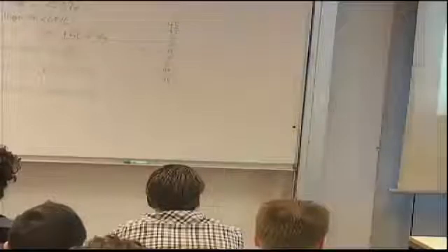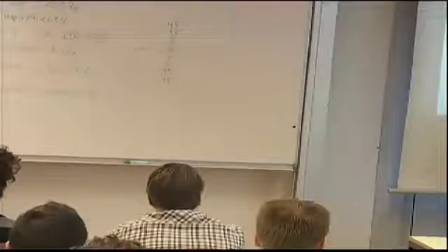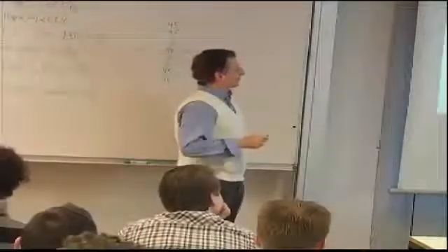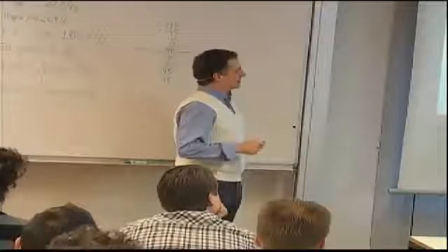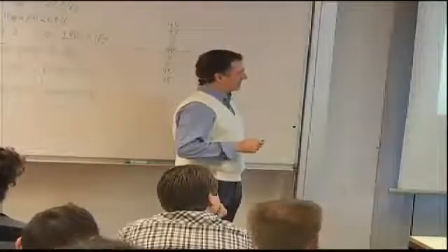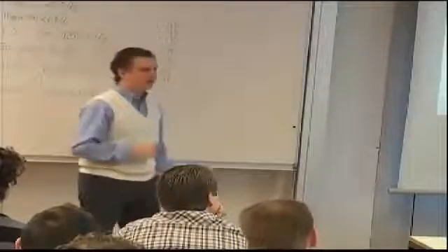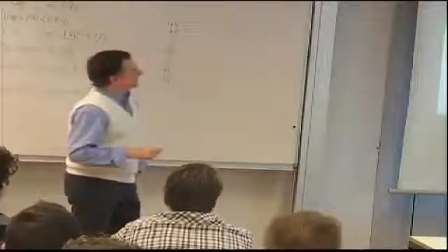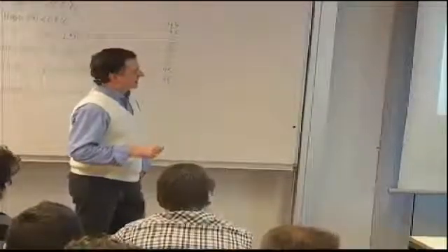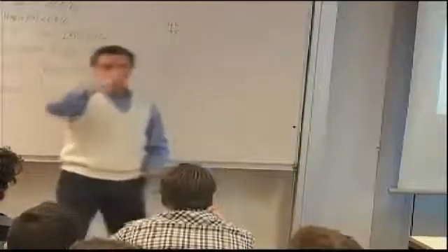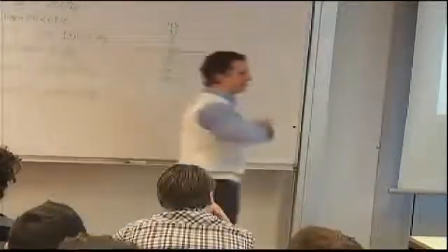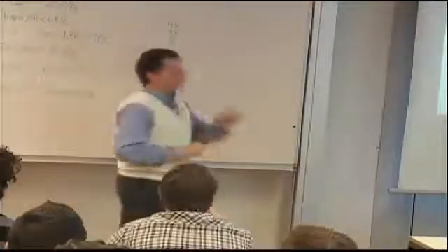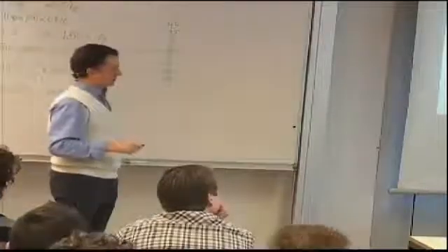In order to do that, we need to determine the stresses for this problem, and we make some assumptions. It's a homogeneous orthotropic plate. The layup is symmetric, so the B matrix is 0. That the layup is balanced, so the A16 and A26 terms are also 0. That's just for algebraic purposes to make it slightly easier. And we are assuming there's no twisting, bending, coupling. We mentioned last time, I believe, that if you have anti-symmetric layups or layups using only 0s and 90s, or I'm telling you now, layups using only fabric material, plain weave fabric preferably, then the D16 and D26 terms are 0.